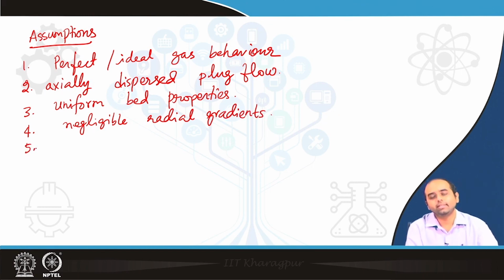Since we are dealing with a problem of gas, and gas diffusion is generally quite fast, it is reasonable to assume that in the radial direction, where you mostly have diffusive flux, the diffusive flux is too fast. So, there is negligible gradient along the radial cross section.